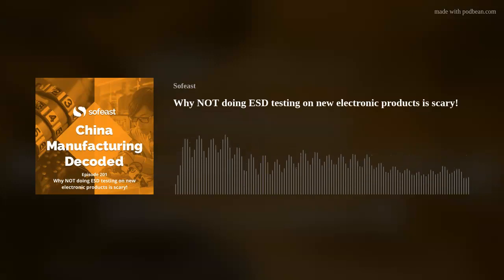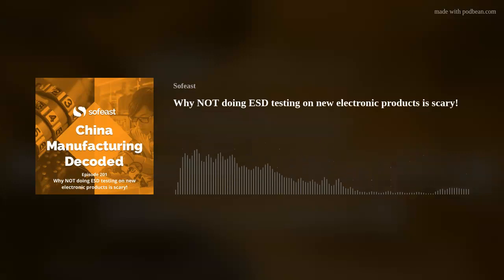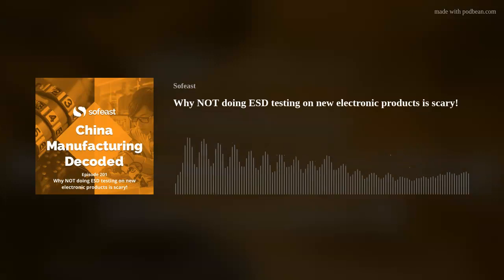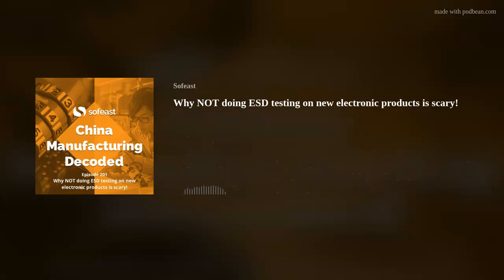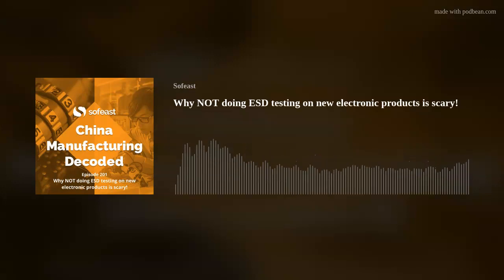Yeah. Then proper grounding techniques. We talked about, for example, personal grounding like wristbands connected to workstation grounding, and even equipment grounding. I'm glad I remembered that. That's when you've got equipment that is actually testing your product. And boy, imagine if it's not grounded and you just touch it to a PCB, your board is toast, or your chip on board is toast. It could happen. And believe me, a lot of the design engineers have a lot of stories to talk about.